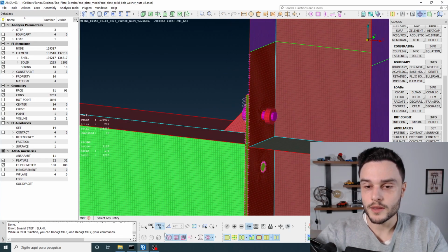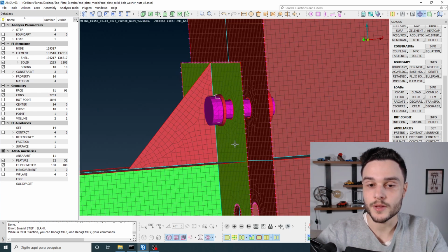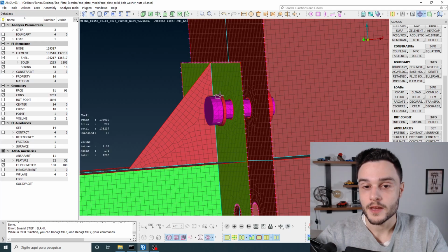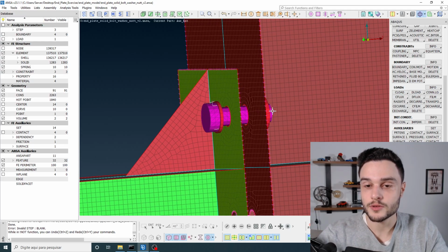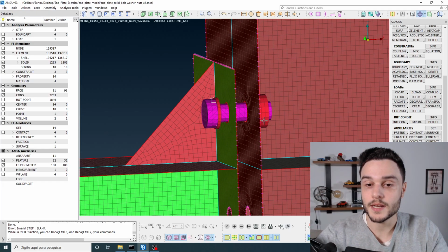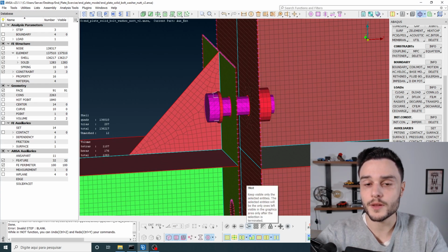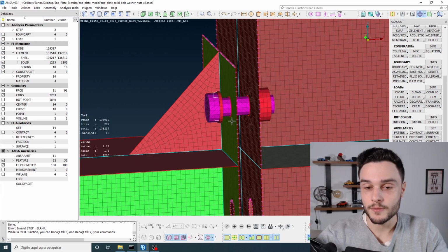So when we are using commercial items, so when we use a bolt that we have chosen from a catalog and a washer and a nut chosen from a catalog, we don't need to validate the threaded region of the bolt and nut, because it has been validated previously already. The only thing that we need to validate in an FEA model is these.